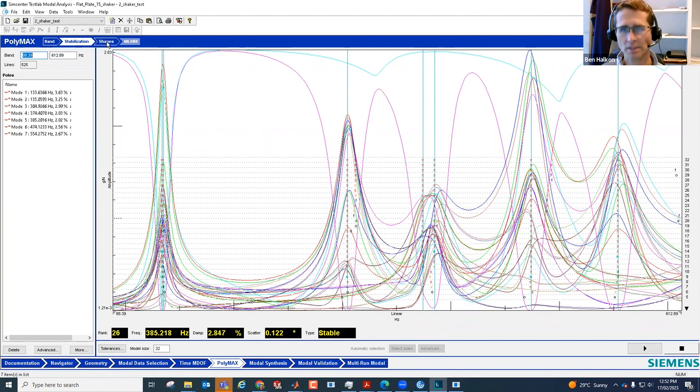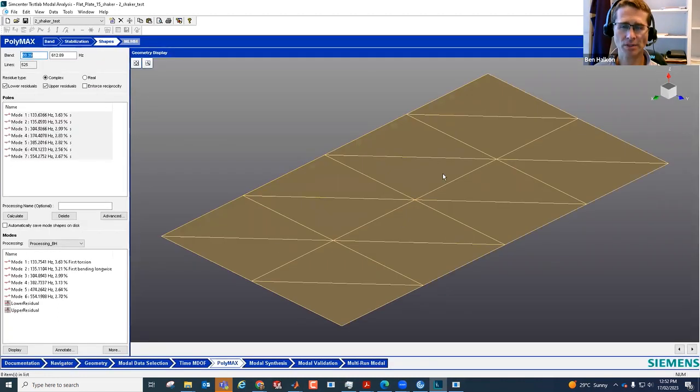It's very hard to know that as a junior vibration engineer. These are the sorts of things that come with practice. Different structures have different frequencies, different mode shapes. You have to be able to understand something about what to expect to be able to interpret these measured data and properly select these frequencies. We can also use finite element analysis to help us compare and contrast our experimental frequencies with our simulated frequencies, and that's something that we will also look at in this tutorial subsequently.